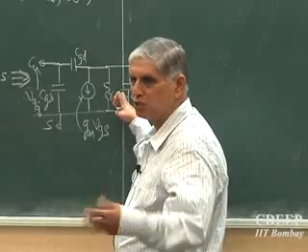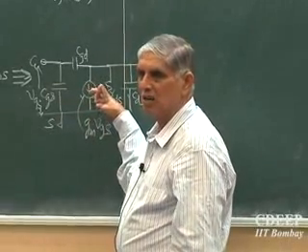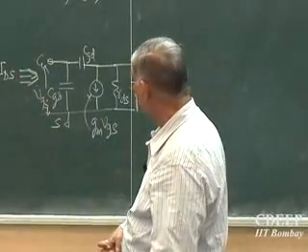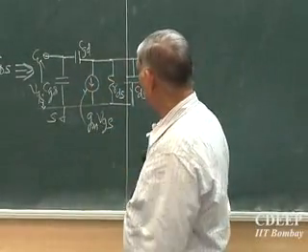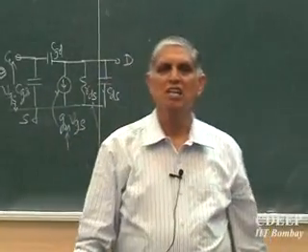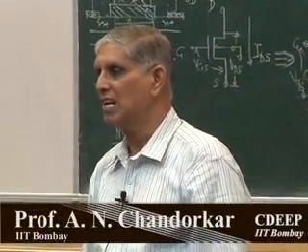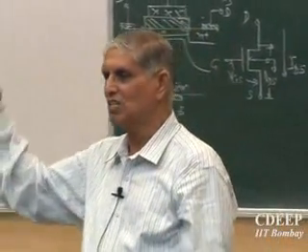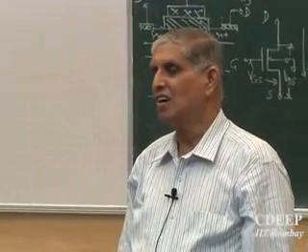This RDS is the same as 1 upon GD. Yesterday I said GD, so it is the same thing. So this equivalent circuit is my goal, and then I want to know how much and how they are related. Now, an interesting thing which you all should know: this is called the small signal equivalent circuit, the AC equivalent. The terms which are interesting there are gm and RDS, of course these are capacitors otherwise. Both these terms, RDS as well as gm, are AC values. But to our great amazement, they are directly related to their DC equivalent values of IDS, VGS, VDS. So knowing the exact DC values of VDS, VGS and what current IDS I get, I will be able to derive the expressions or values of the AC terms, gm and RDS.